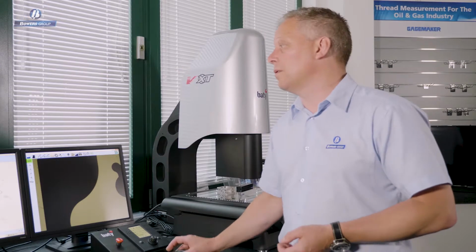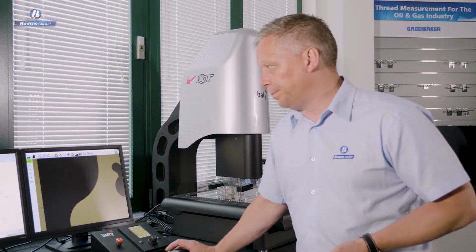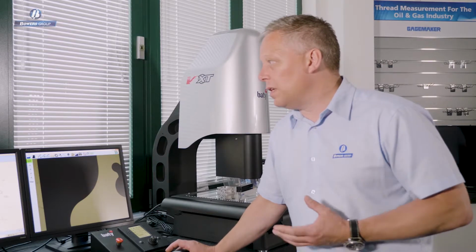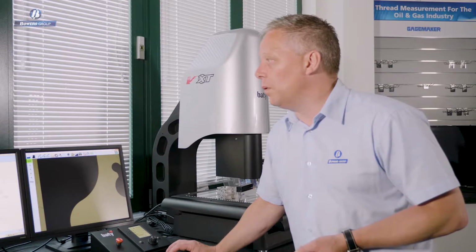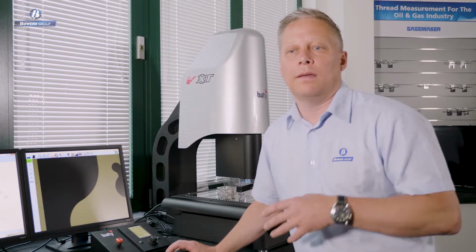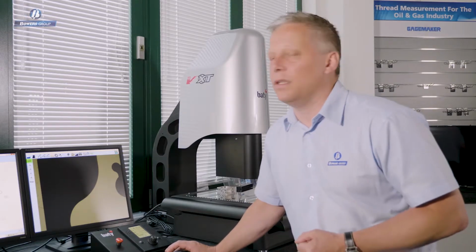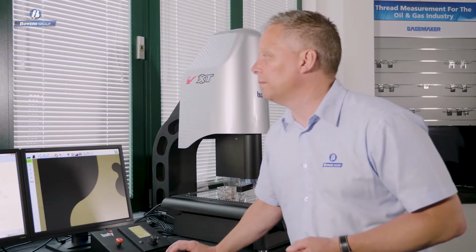So, having used the curve profile scanning tool to create this point cloud, what are we going to do with that data? Well, the most convenient way of using that data, I think, is to import a DXF file so that we can compare the data to the CAD profile and see how close it is to the nominal profile.